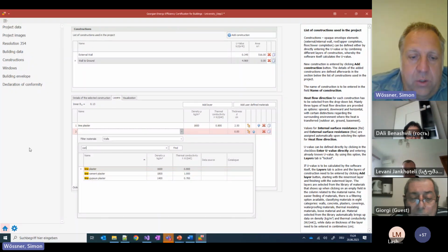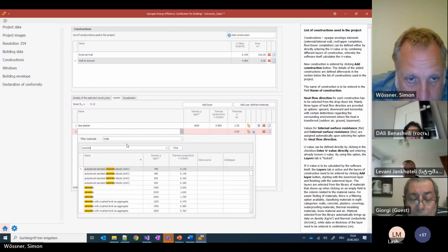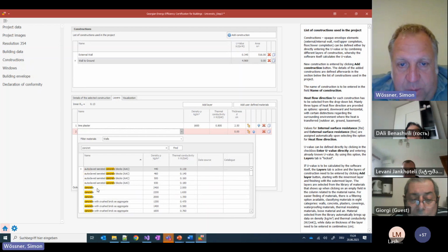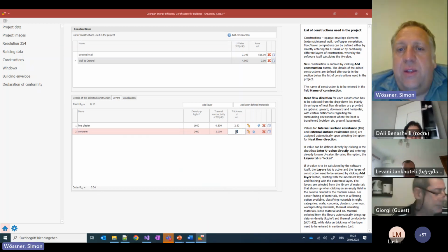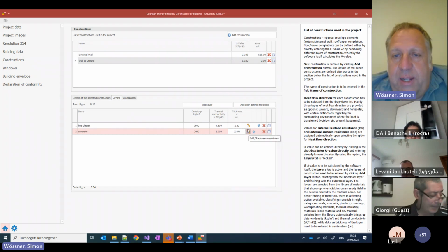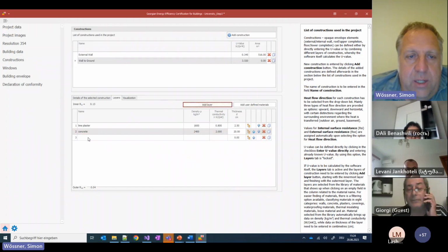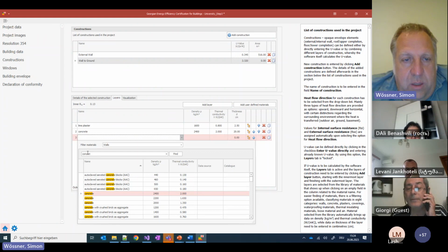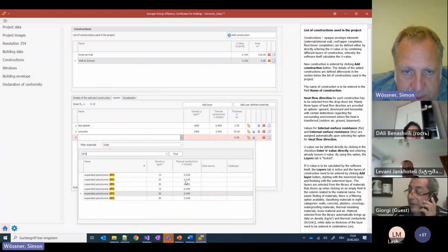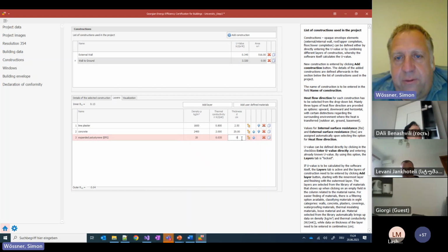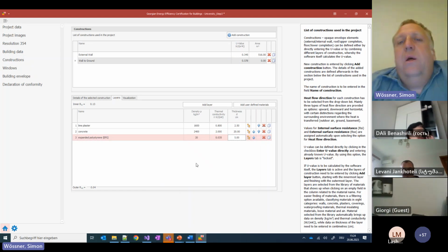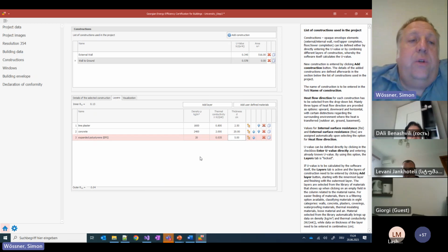We go to concrete, select one of the concrete systems here, give that 20 centimeters. And then we have the EPS. Look for the same material, 5 centimeters. We entered now the construction.